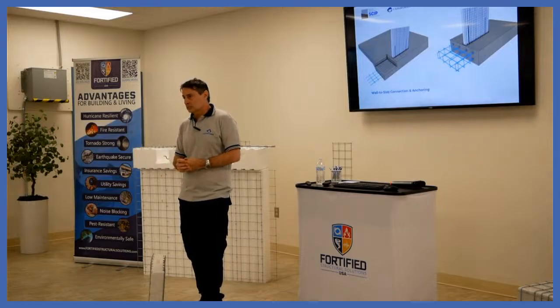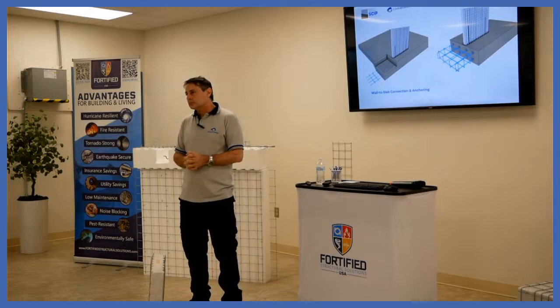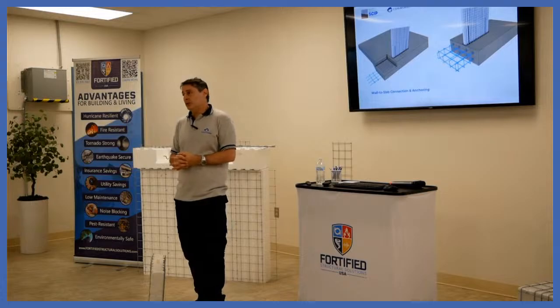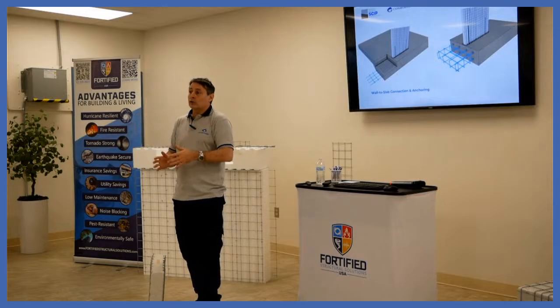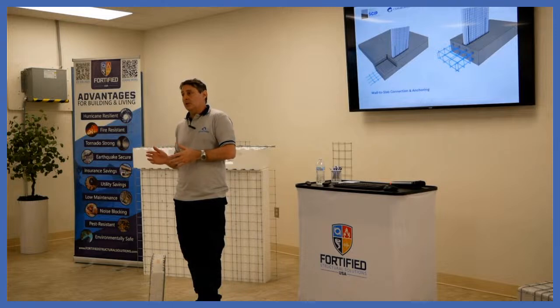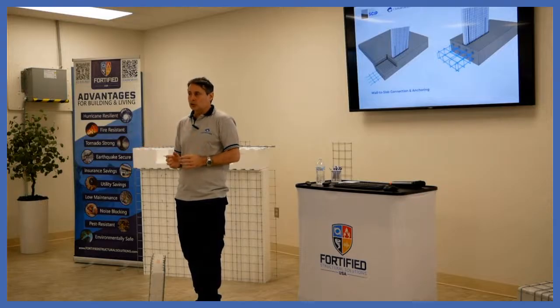One more question. Back to the same 8 foot, 10 foot slider, if we have to put a cast in place header there, do you expect a cast in place column on those sides, or can the panel handle it? Usually when there's some concentrated load, you have to add a little more room for concrete or mortar. So it does happen that there are places where I have to melt a little bit of the wall, for instance, to make room for some internal column. So it is possible.